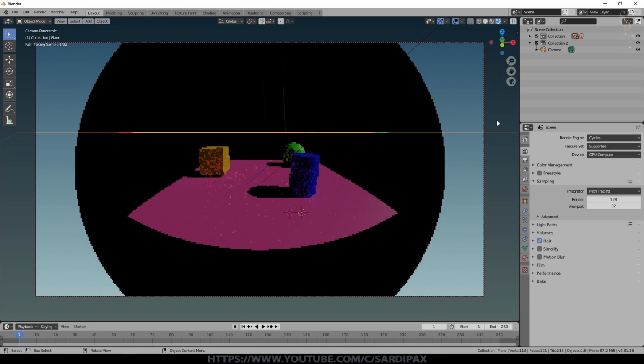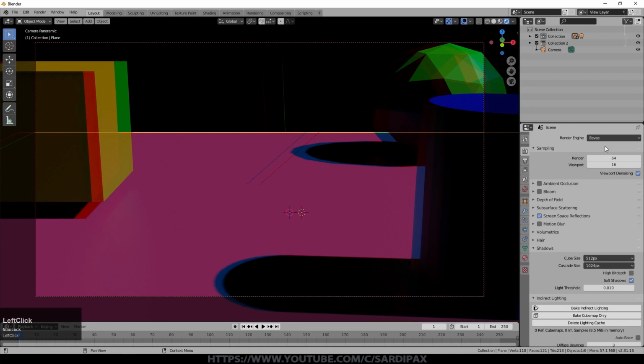That's how you get a 360 video. If you want to do a 360 currently, whether it's 3D or otherwise, you'll need to do that in Cycles, and Cycles obviously has its limitations. So I decided to do it in Eevee because one of the other considerations of a 3D video is resolution. Obviously that's a consideration anyway, but because you're rendering two eyes' worth, you're effectively creating two separate scenes from a slightly different perspective. You're having to render twice as much, and then you're having to display twice as much.